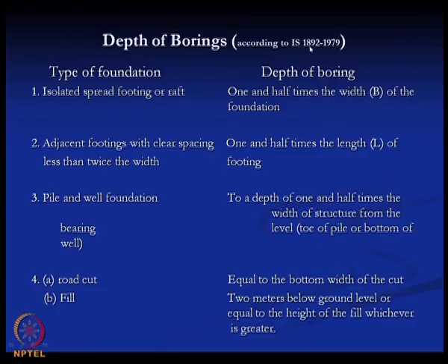That is IS 1892, 1979. So, according to that, what would be the depth of boring? Now, if the type of foundation is an isolated spread footing or raft, the depth of boring will be 1.5 times the width of the foundation. This is the minimum required depth of boring for an isolated spread footing or raft foundation, 1.5 times the width of the foundation.